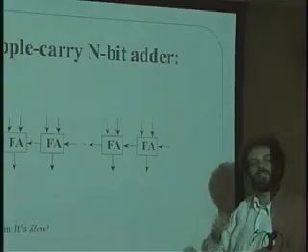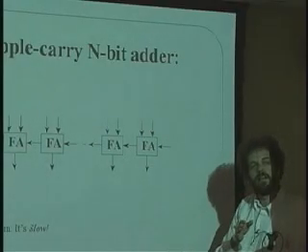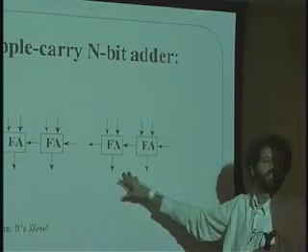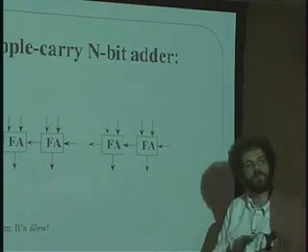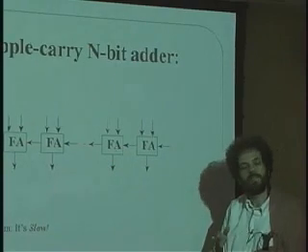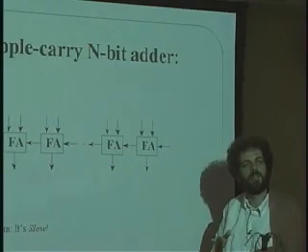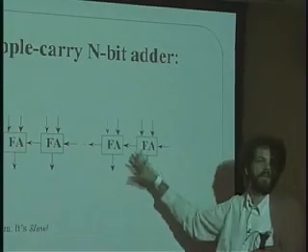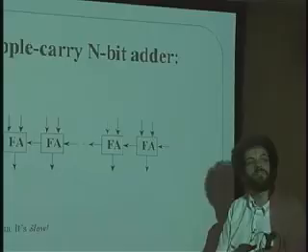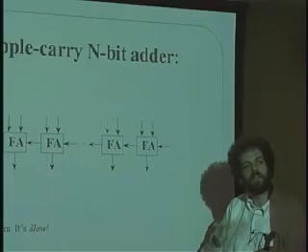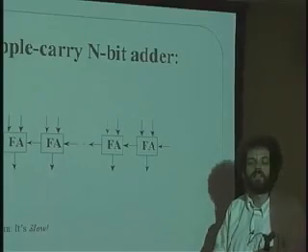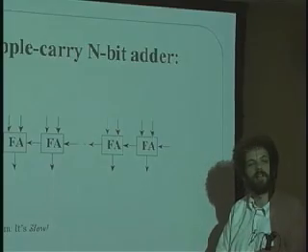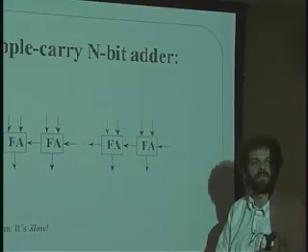And maybe you actually clock your computer at a different speed depending on how long it takes the adder to get its job done. In the later part of the course, we're going to talk about different ways of clocking the processor, either slower or faster, in a data-dependent way. So sometimes adds are easy to do, sometimes adds are hard to do. Why not take advantage of when they're easy and clock the machine faster? It's something that's not usually done, but in the highest performance systems that are out there, they are starting to do it now.